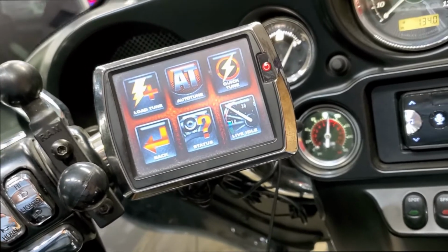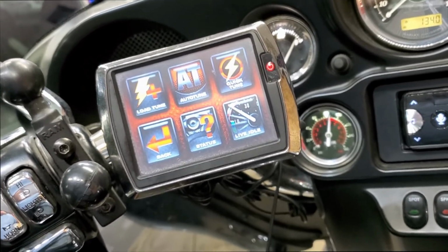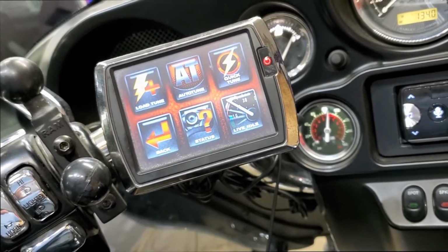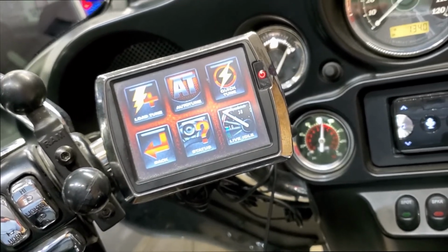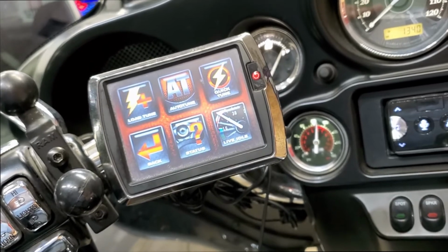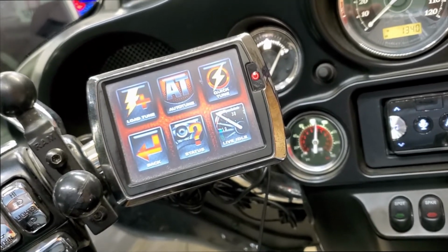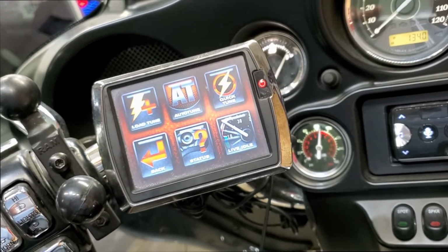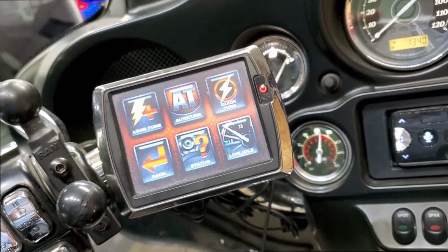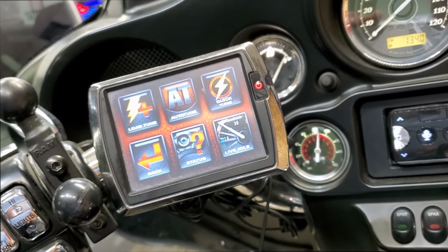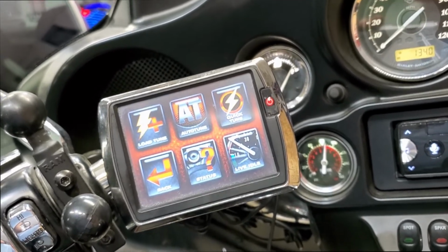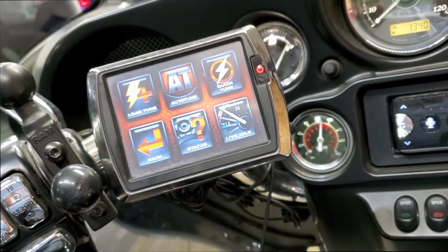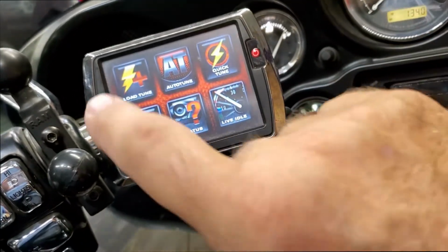So you want to retune that, because then when it sees that 10.7, I'm making numbers up, the next time it says, oh, at 10.5, that's the real number I want. Change to 10.5. You go out, ride it a third time. The bike says, I see it's set for 10.5. I like 10.5. I'm going to leave it at 10.5. But you've got to do a couple auto tunes to get it to that 10.5 level. Again, using generic numbers, things like that.